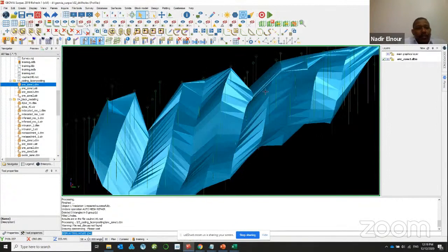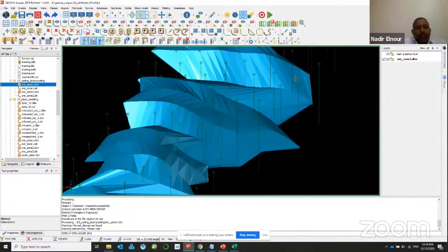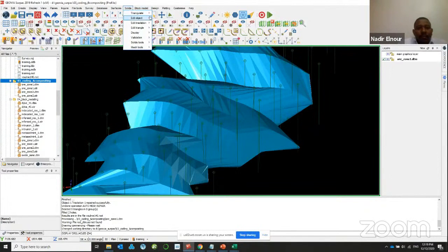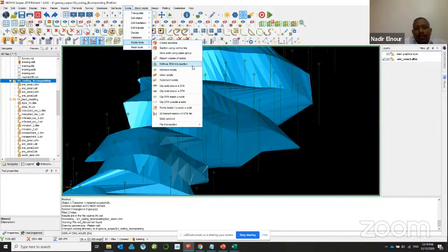This also is very easy. Just set the working directory. Then you come here from the solid tools, and then you can get a drill hole 3D intersection, and then we'll code your domain to the drill holes. So you already know that you already digitized this one from the geology, but sometimes the geology cannot represent the grade, so you have different grade from the lithology, because of different domains, or you combine multiple domains. So you need to flag this back to get the sample information within this data.